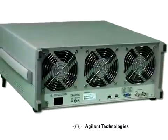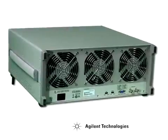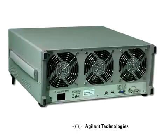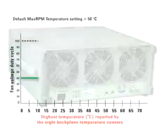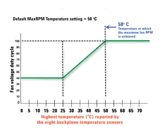The M9018A has 3 large fans which are used to expel hot air. We can control the temperature inside the chassis by controlling these fans. A user-settable fan control algorithm is used to control the fans. Notice that this algorithm is controlled by the maximum RPM temperature set point. This is currently set to 50 degrees Celsius, which is the default value.